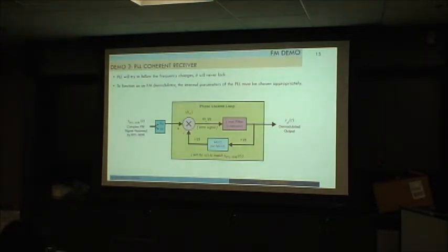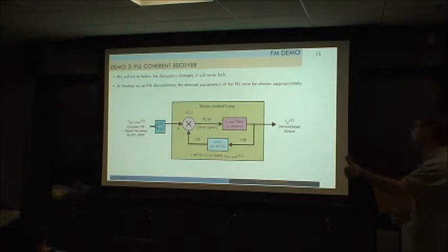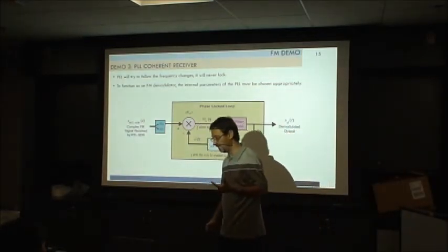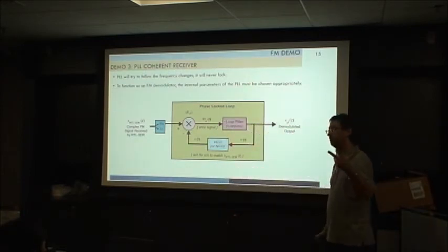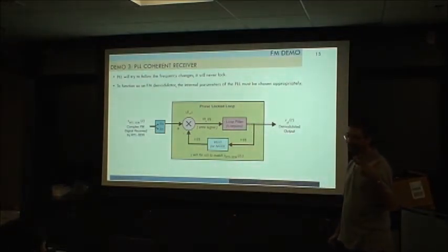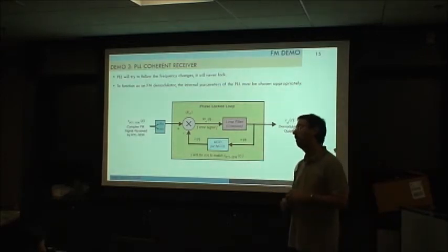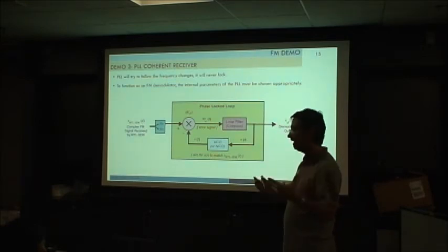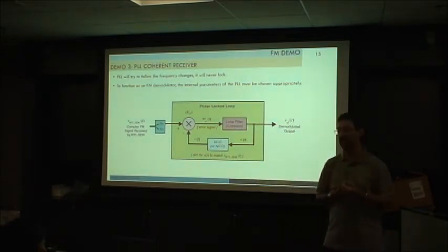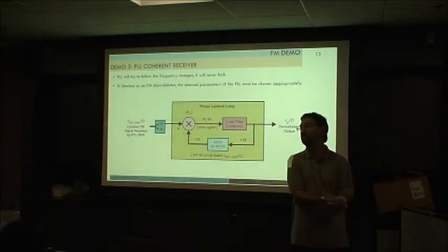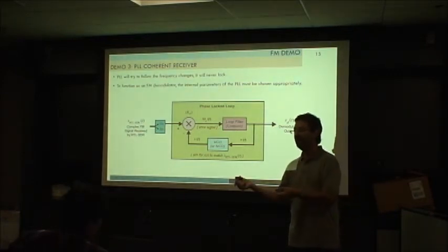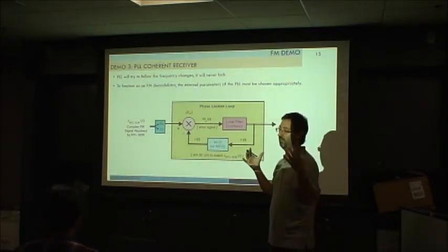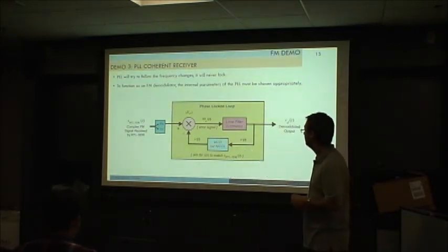And the last, let's say. So we have the differentiator and the phase shifter, and you could see like a third, the modulator, that maybe you did on some analog FM lab. I don't know if you did it, but in an analog FM lab, what you do is have a VCO as a transmitter and a PLL as a receiver. Basically, that is how analog FM works, if you sometimes take some lab.